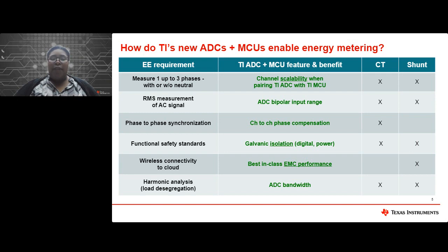You'll also have the phase-to-phase synchronization. However, that is only in the CT implementation. The next thing is you will have functional safety standards. So you're going to get galvanic isolation for both the digital and power measurements.